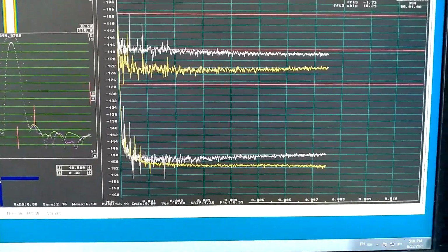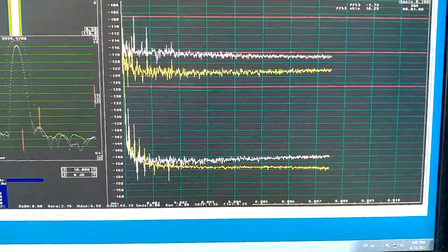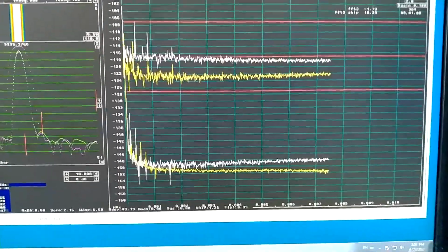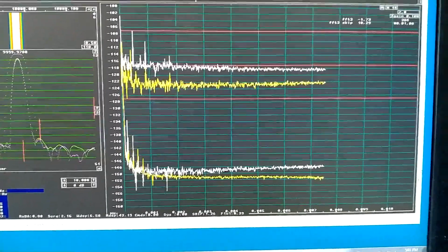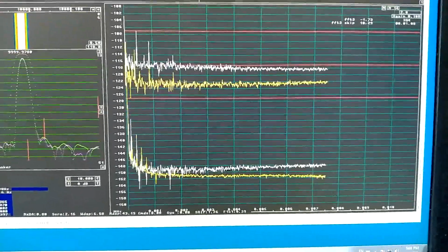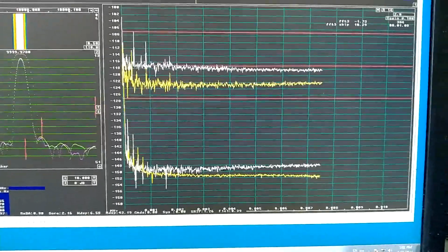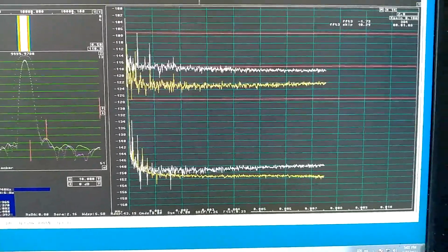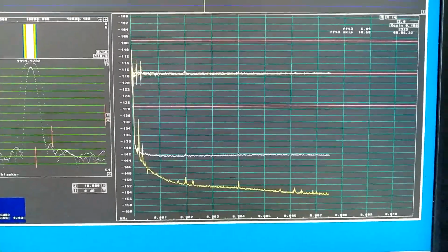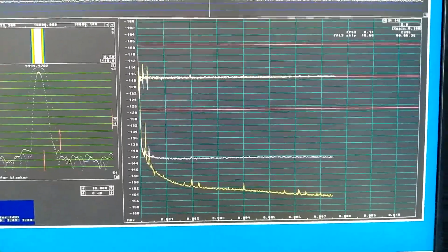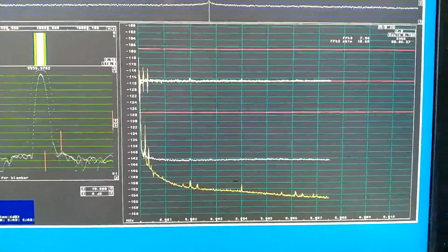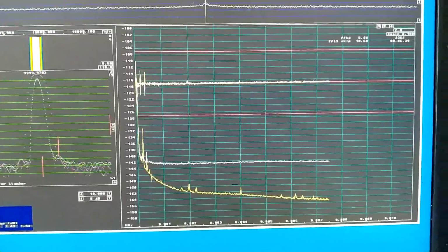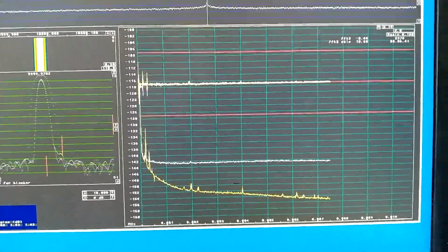It was minus 152. A little bit above that. So there is a significant improvement, but the amplitude noise was before minus 148. Now it is minus 142, so it has increased significantly by the application of amplitude limiting.